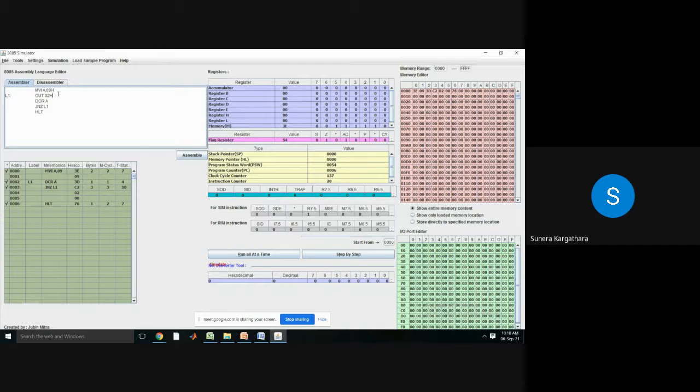So that means my display is happening on output code 2, right? Whatever my count value is, I am sending it to the output code and I am decrementing it. In between this, I need to write some loop which will execute for a certain finite period of time, and that is for nothing but passing my time. Are you getting my point, student? The loop I put here will not do any work, but it will only be used to provide a delay in between.